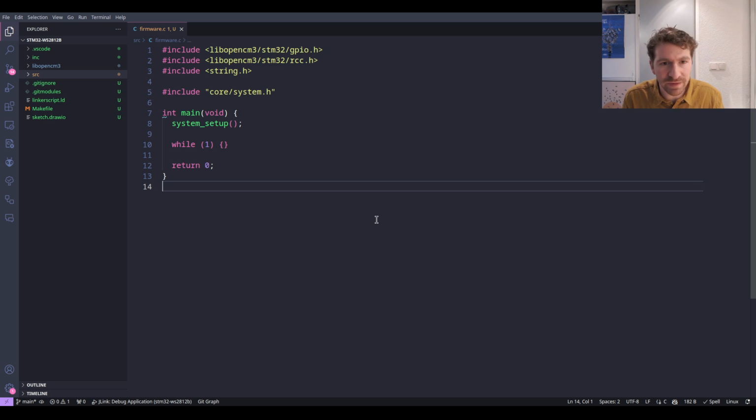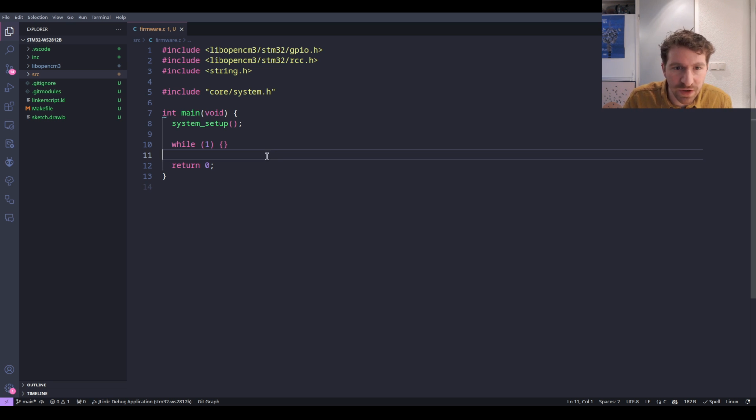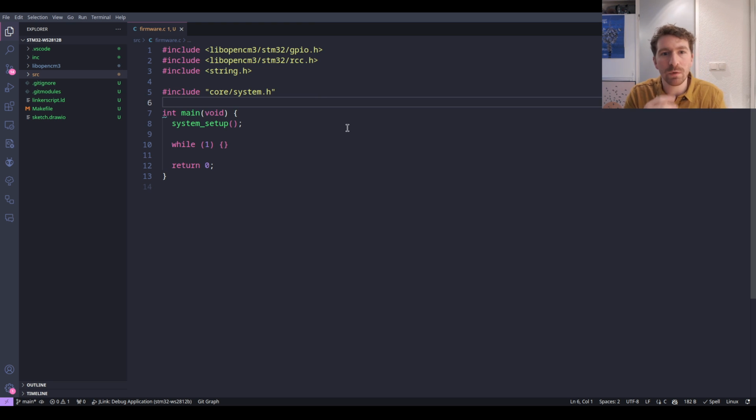Yeah, alright, I think we're ready to start up here. So the first thing I want to do is take the chip and start trying to generate some of the timings that are involved in that signal, right? So I want to be able to bring a line high and hold it high for like 400 nanoseconds. That's my aim now.